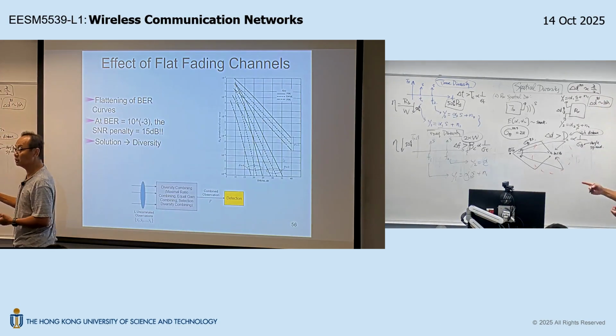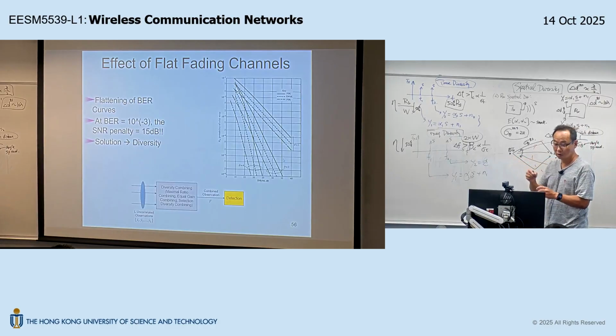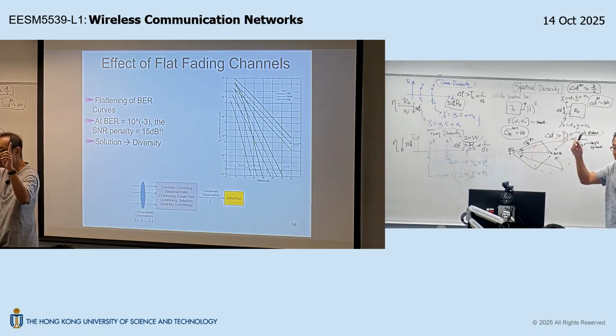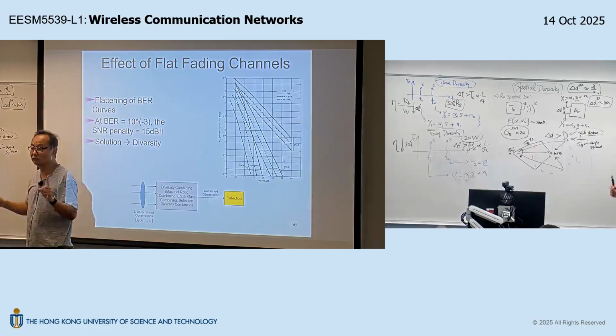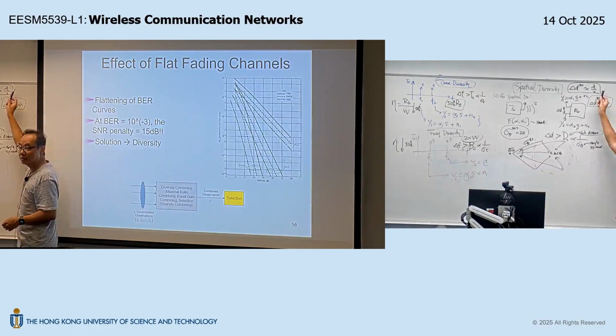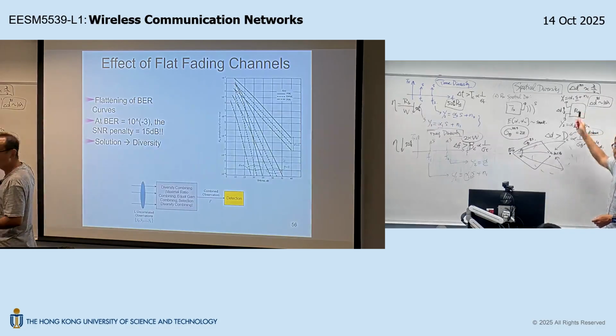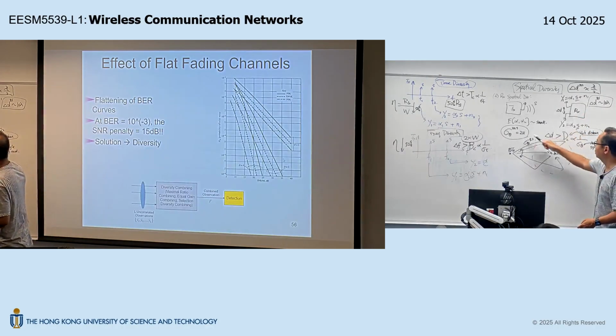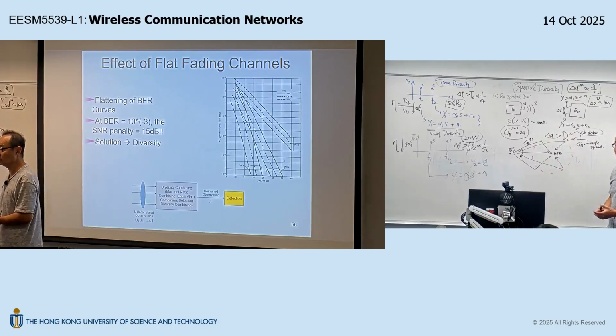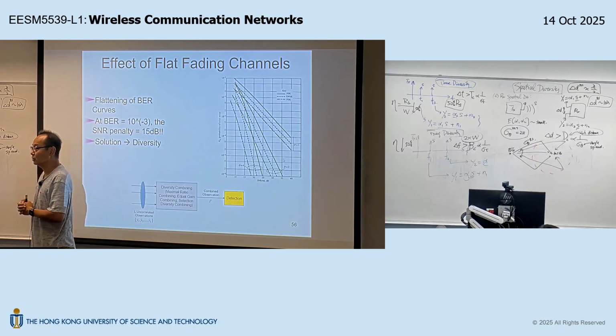Okay, so at the base station side, if the base station is the receiver, the separation of the base station antenna needs to be at least 10 times the wavelength. So don't take this half wavelength as the holy grail. It depends on the angle spread. The half wavelength is under the assumption of homogeneous scattering. Is that okay?